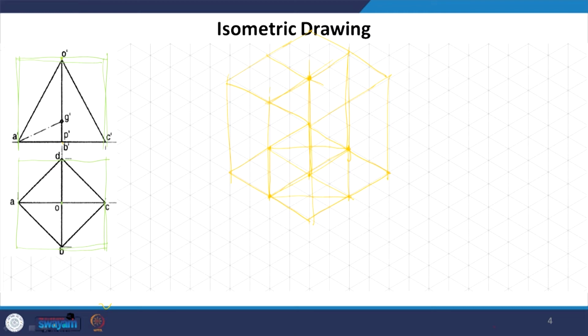Whichever way I do, simply because I know that this is a right pyramid, this axis is perpendicular, so I will get it parallel to the z axis. That's what we know. If any line is parallel to an axis, it will remain parallel to the axis, the three axes. That is what we exploited and we got this point. So, now we will finalize the projection here.